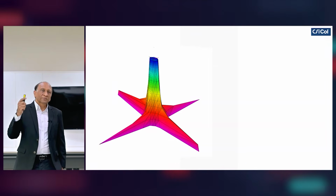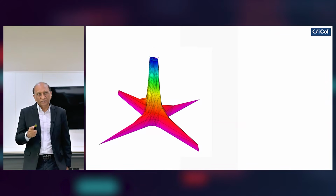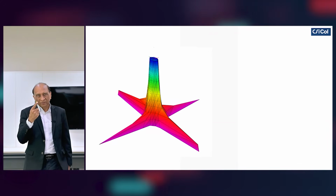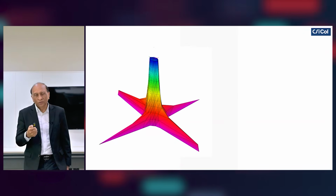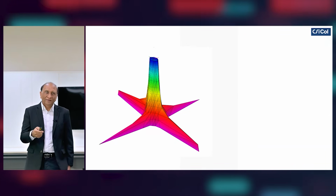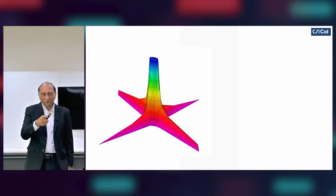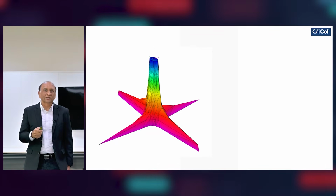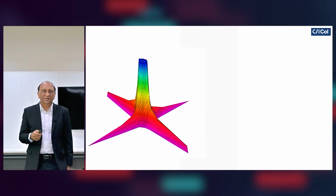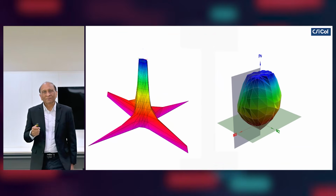So I mentioned earlier that axial load has a relationship with the moment curvature, because of equilibrium and because compressive load can consume most of the concrete capacity. So when your compressive load is increased, the curvature capacity reduces. As you increase P, curvature capacity reduces. And this is a plot that you can see, and you can compare it with the PMM diagram.